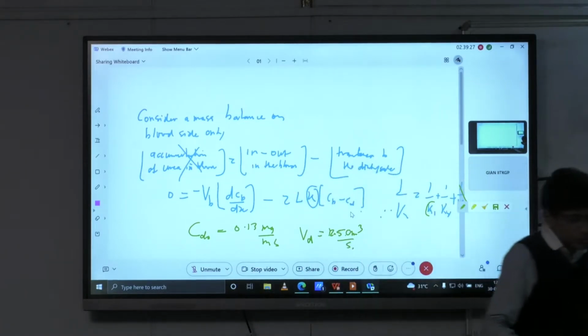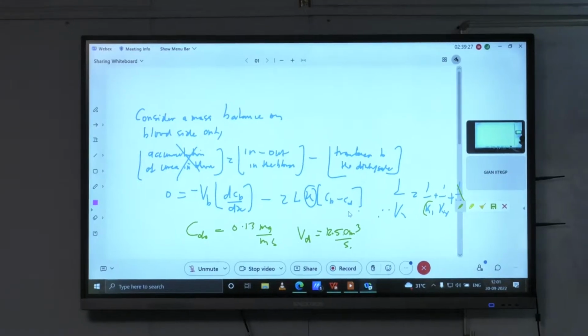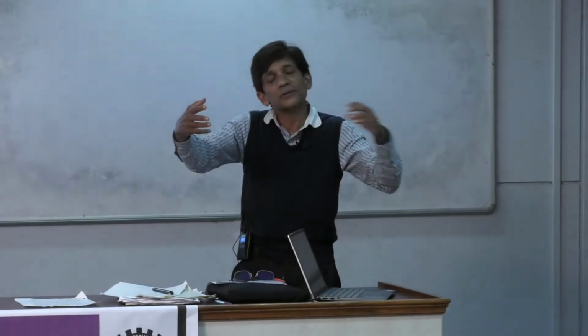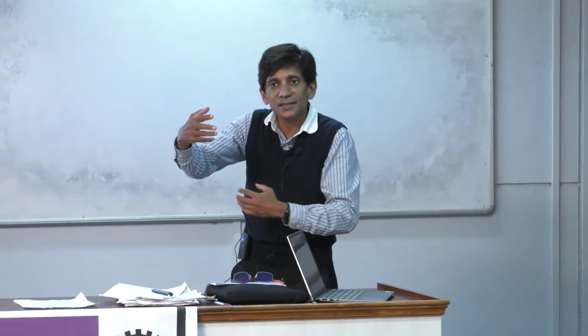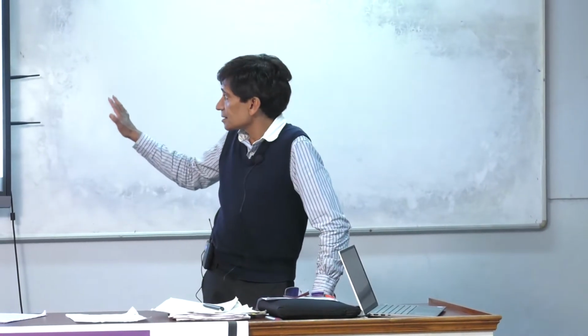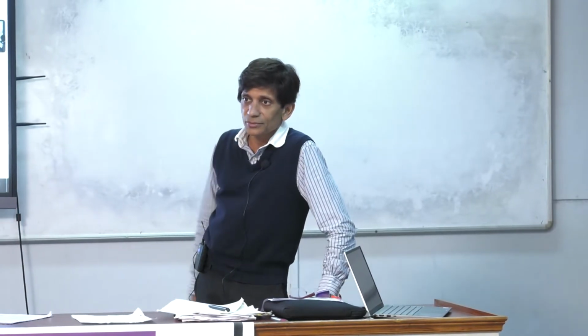So, for those of you who are not engineers, maybe you can see that the way we're trying to calculate this is you have two flow rates, right? The blood side is fixed. You're asking yourself the question, what do I have to do on the dialysate side to achieve my separation, okay? Also, the membrane area is fixed this time. You can't change that. You've got a dialyzer, okay? And then for chemical engineers, I'll give you the actual full solution, but that's the way you would solve it.